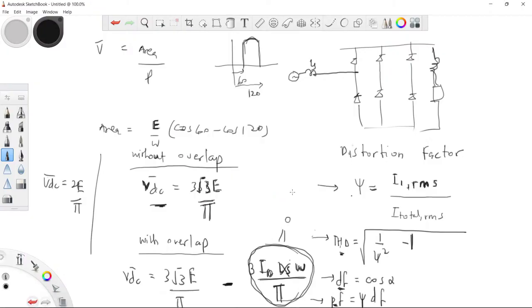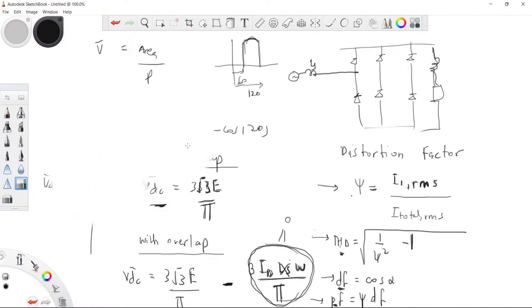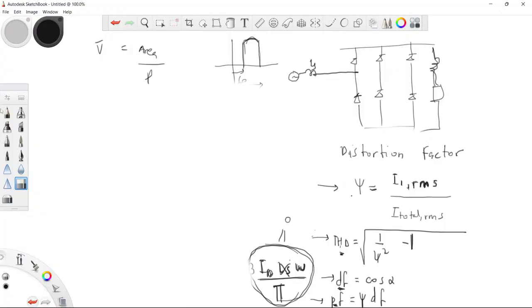Alright. So we have it like this. Now we've also seen that the output current flowing through the load is not a sine wave as we expect, but rather quasi square like this. This angle here is 120 degrees, and we will see what this angle is. We say it's made up of harmonics. This value is plus ID and this value is minus ID.